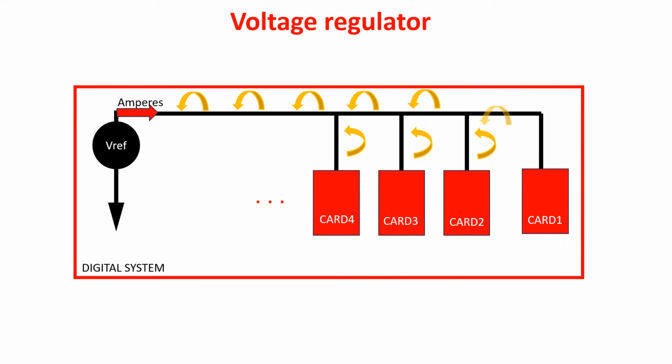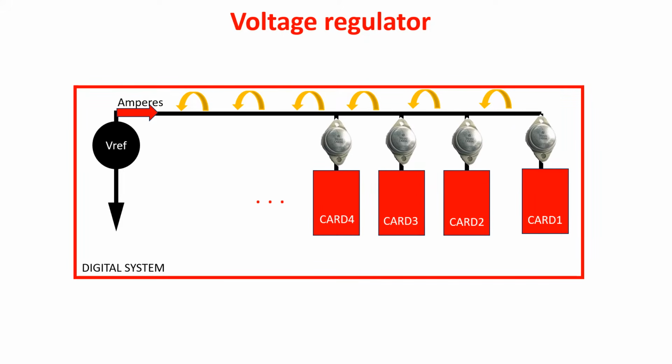This is aggravated further with TTL logic, as it draws transient currents many times the steady-state current when it switches. These problems have created a considerable interest in on-card regulation, that is, to provide local regulation for the subsystem of the computer. Rough pre-regulation can be used, and the power distributed without excessive concern for line drops. The local regulators then smooth out the voltage variation due to line drops and absorb transients.